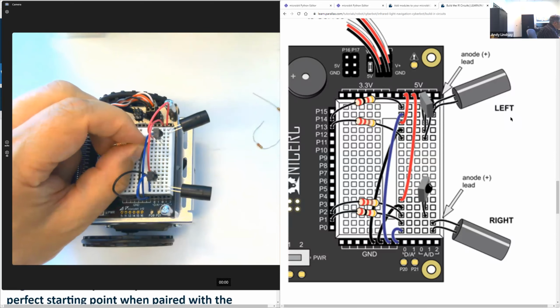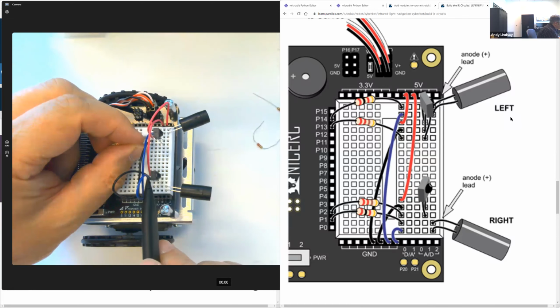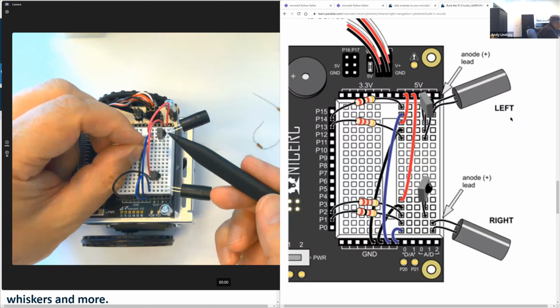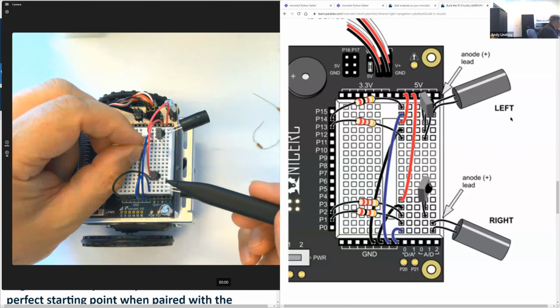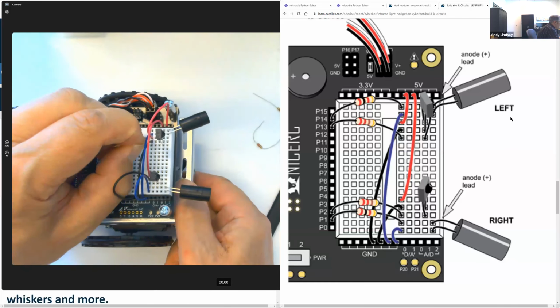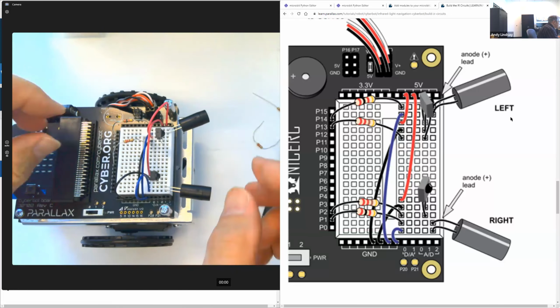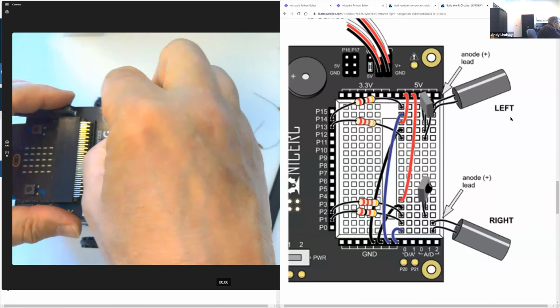Oh, incidentally, make sure to keep your power turned off, and we'll check before we turn the power back on to make sure that the black bump on the face of the IR receiver, a hemispherical bump, is pointing forward. So we'll go through that. Everybody keep your power off, and we're going to do a checklist of items to check before we turn the power on.